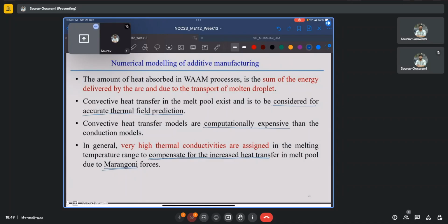So the surface tension of the liquid will be the least in the center, where the regions are the hottest, and the surface tension will be highest around the periphery, where the temperatures are low. Because of this difference in surface tension, certain forces will be exerted on the free fluid surface, leading to convection from the center outwards towards the periphery.